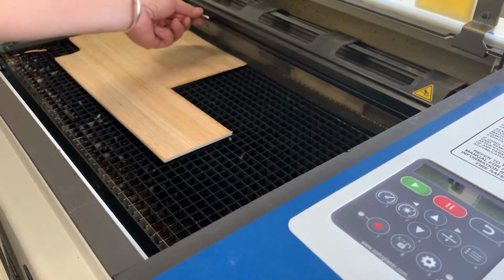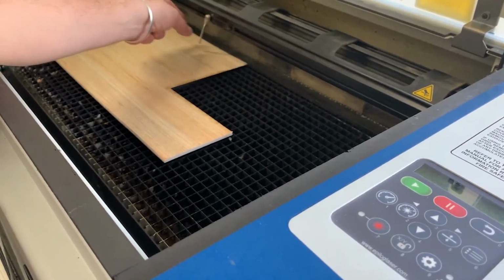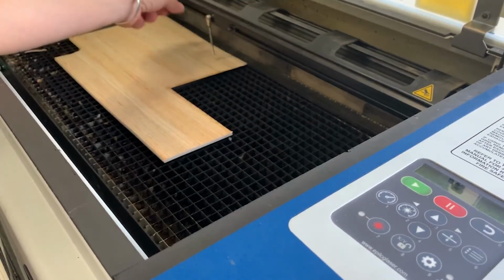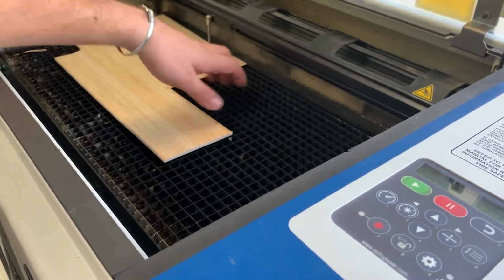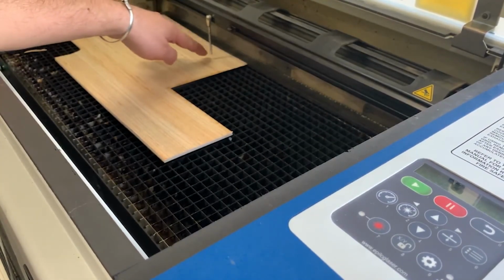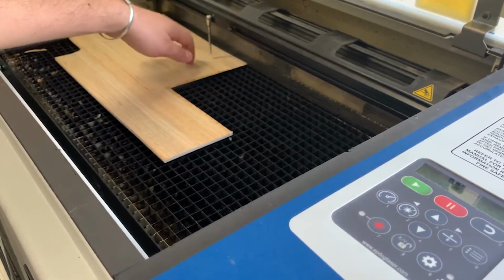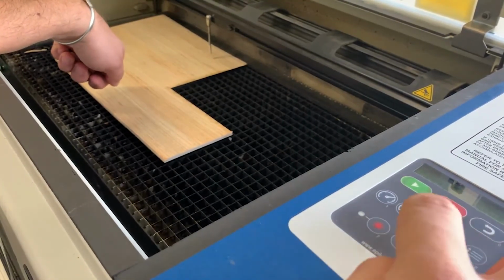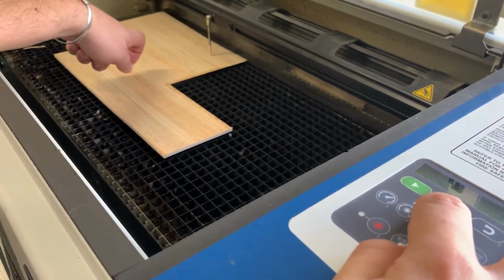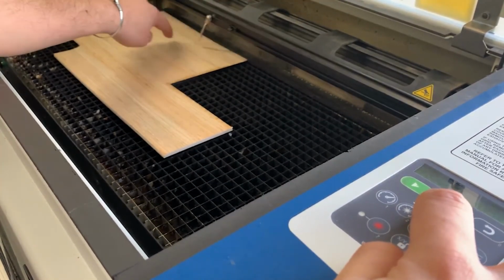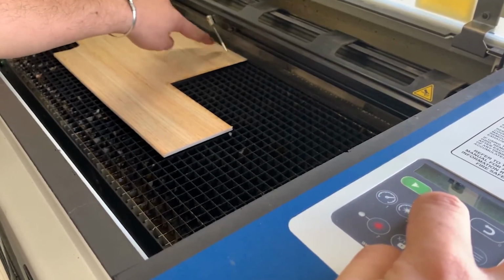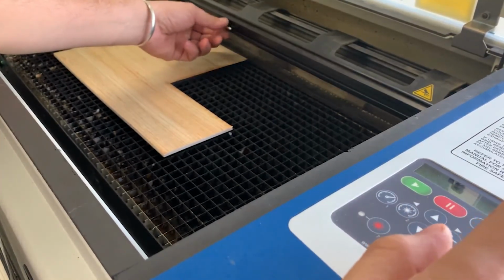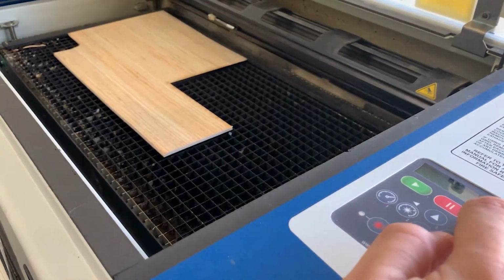Okay. You're going to take the slider right here, drop it down. It's just kind of magnetic. You don't need to click it out or anything. You just drop it down, you rest it up there. And you need to move the bed of the laser up and down so that the edge of the focus tool meets the edge of the surface of your material. Okay, you do that by hitting the up and down arrows here. So I'm going to bring it up a little bit until it just barely touches. I can swing it and just barely get stopped when it's hitting that material. That's good right there. Okay, put the measurer back up and hit the back button. And it's good to go.